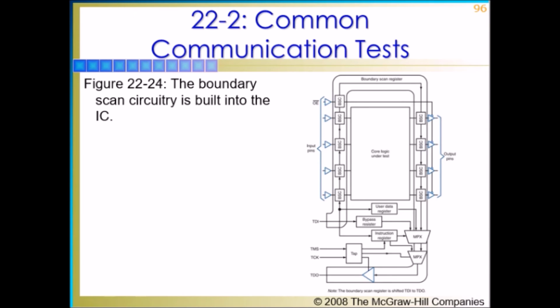The BSC flip-flops are also connected to form a large shift register, the boundary scan register. This register provides the basic storage unit for inputting and outputting data. The input and the output are serial. Serial data can be input to the register via the TDI line.